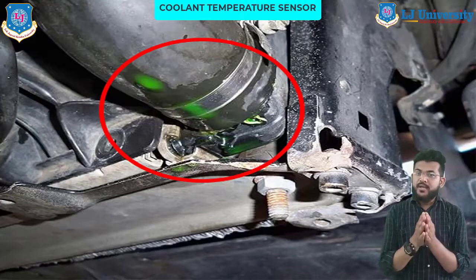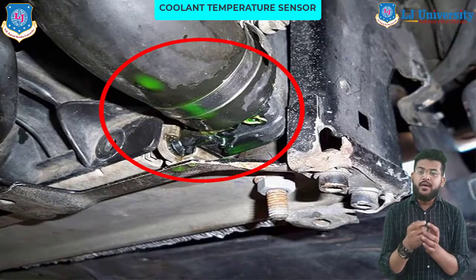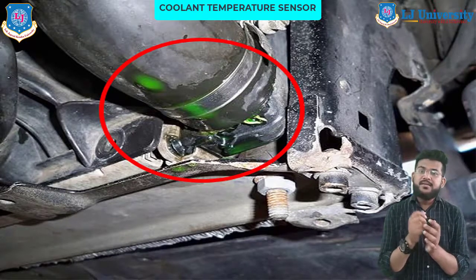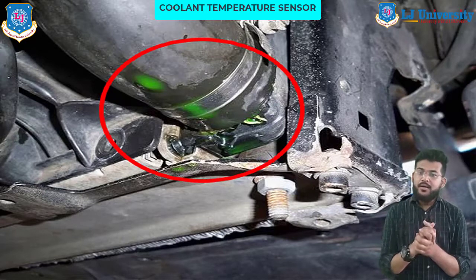So stop the car and look for any coolant. Generally it is green color leakage. So if there is a noticeable leakage, do not drive the car if that is the condition. Instead, tow it to the nearby service station and check for the repair.